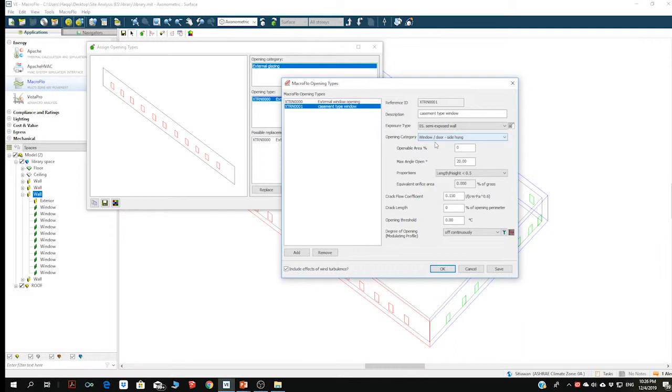Yes, it's not a door, but it's a window. All right, this part here, the openable area, is the amount or percentage of area in comparison to the frame. So normally you cannot really 100% open the window, because some part of the window structure is made of the frame. Okay, and also you have the hinges and so on. So normally we put in 95% or 90%.